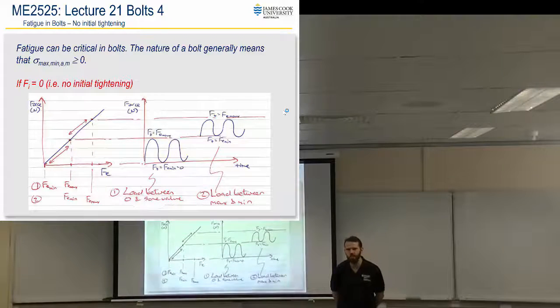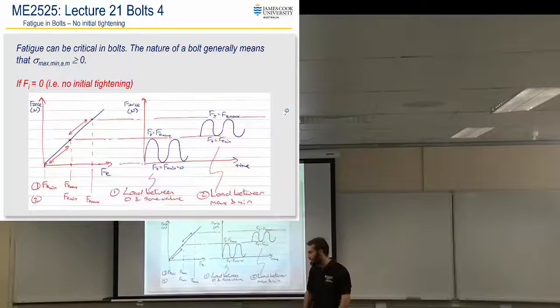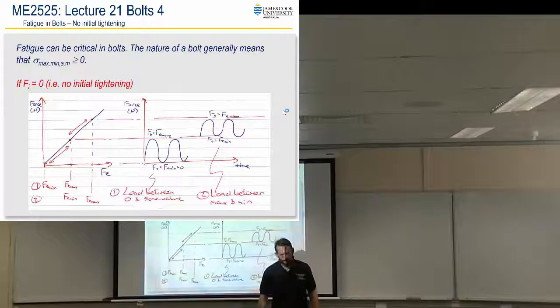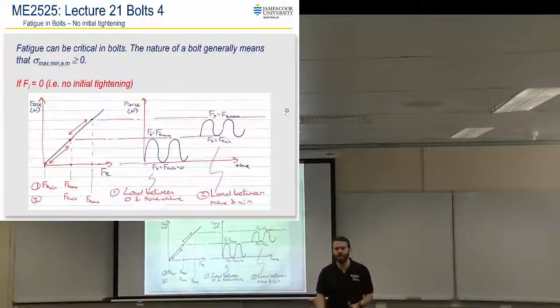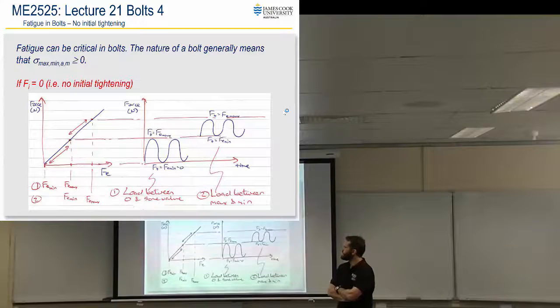When you have a free tension, effectively all we care about is the axial load in the bolt, assuming that you can prove that you don't have separation and that the shear doesn't get dumped on and that sort of thing. If there's no free tension, then we've done static loading for that. But for the case of fatigue, we need to do a couple of little extra things. It's pretty much the same procedure that you've been doing for fatigue thus far.